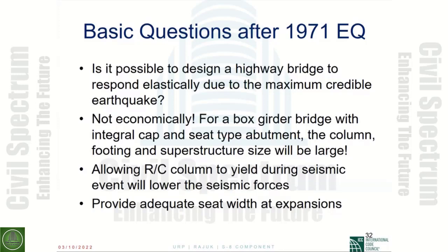So please pay attention that even if you do a ductile design of a column and a ductile design of the bridge based on yielding of the column, it doesn't mean that the biggest earthquake will not damage the bridge. Even though the seismic force is limited by the capacity of the column, the bigger earthquake will cause bigger deformation. So detailing will become extremely important.